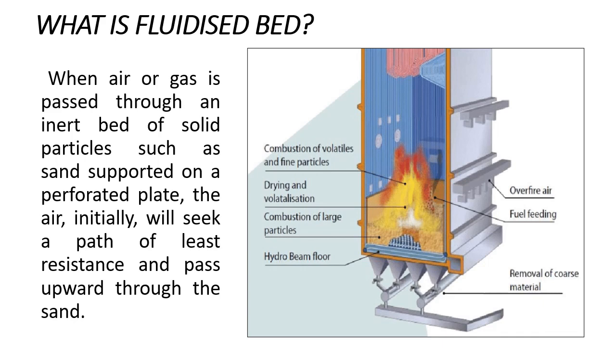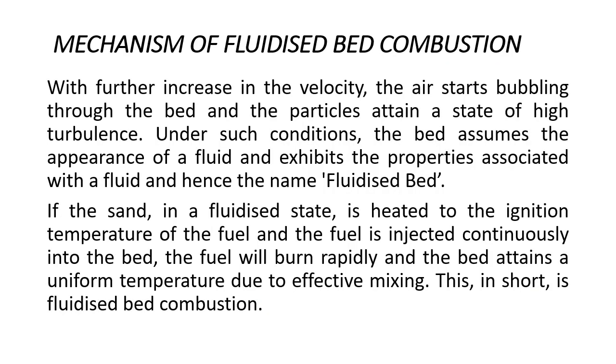With further increase in the velocity, the air starts bubbling through the bed and the particles attain a state of high turbulence. Under such conditions, the bed assumes the appearance of a fluid and exhibits the properties associated with a fluid, and hence the name fluidized bed.